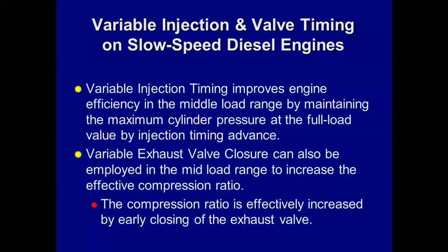So on all the new engines, you're going to see variable injection timing. There's a number of reasons for that, but one of the major ones when you're on heavy fuel oil is because the fuel properties will vary drastically, and your ignition delay will vary drastically.